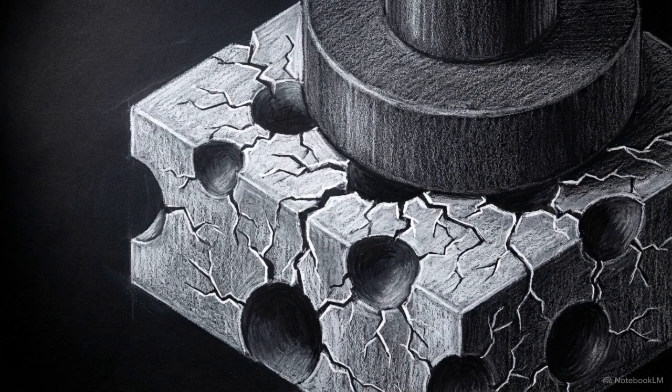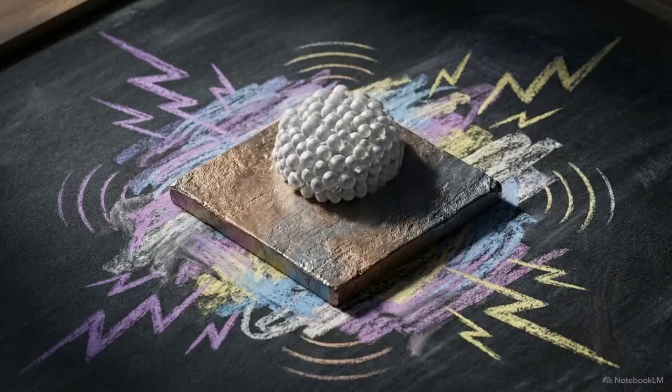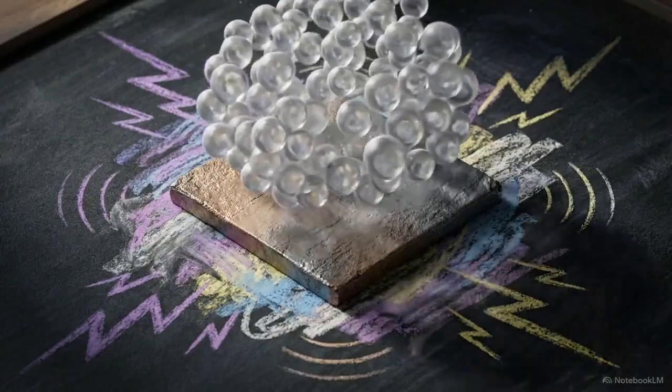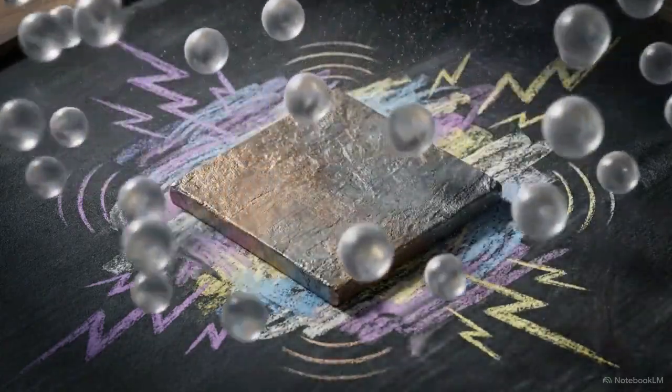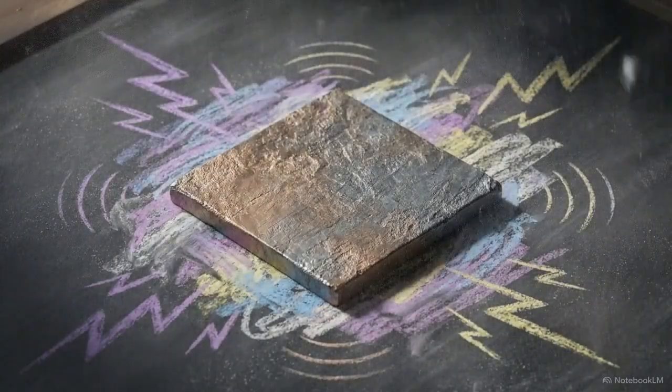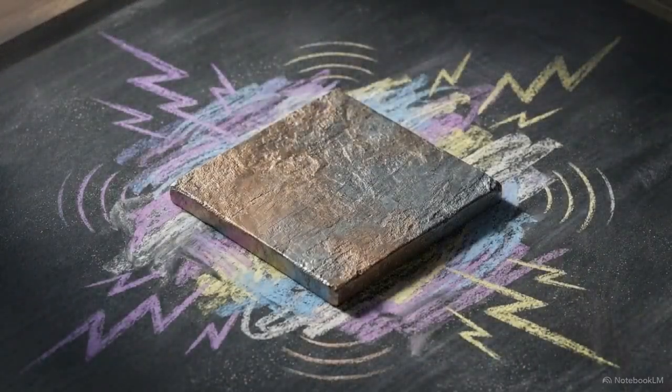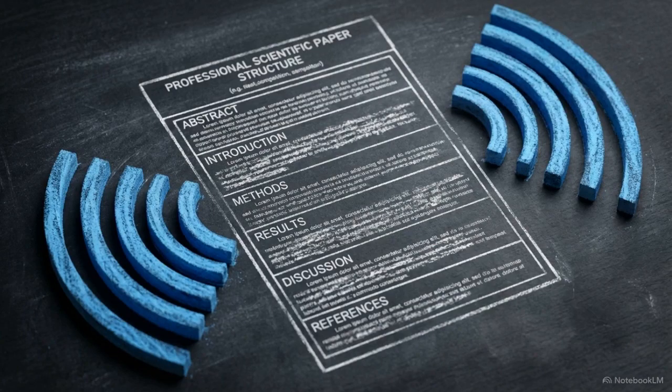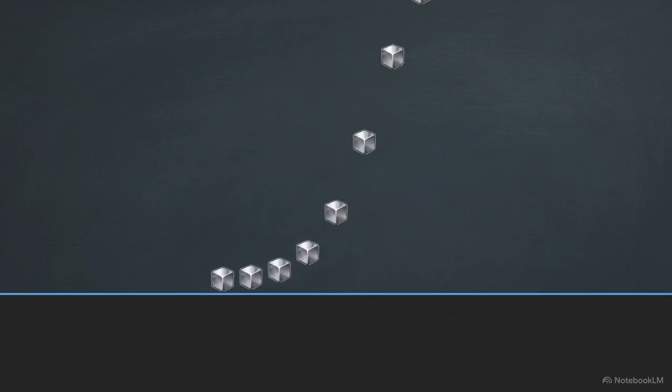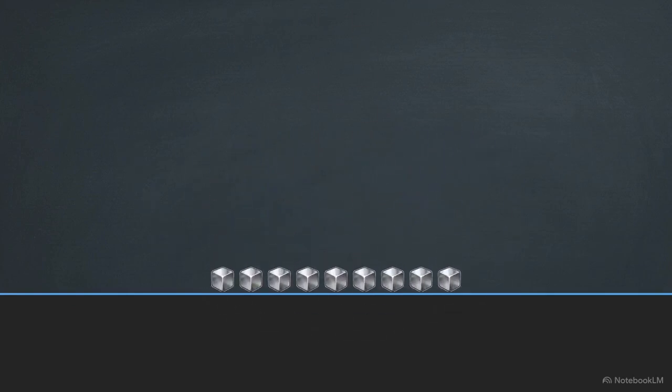weak coating. To clear this chemical bottleneck and prevent defects, engineers introduce high-frequency ultrasonic vibrations directly into the fluid environment, creating intense physical micromixing. Research by Wang and Wang demonstrated that this ultrasonic cavitation, the rapid formation and collapse of vapor bubbles, physically blasts the hydrogen gas away from the nucleation sites before any voids can form.